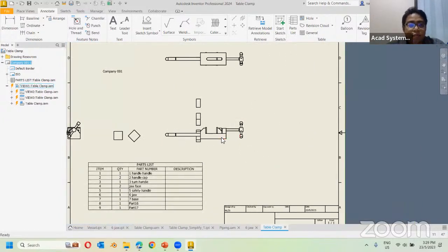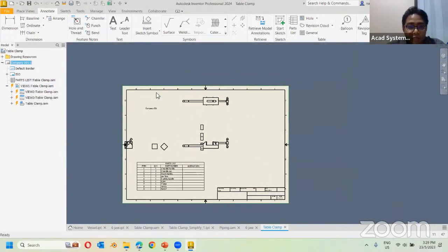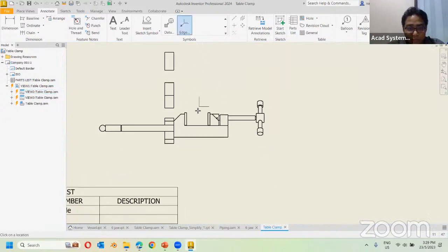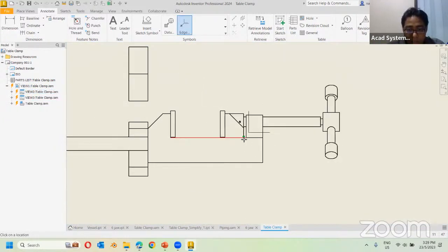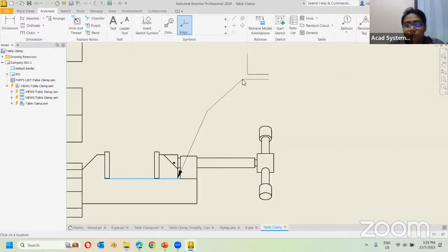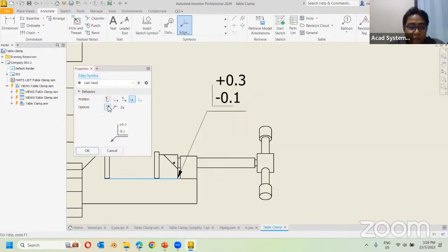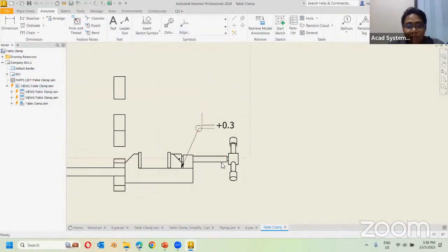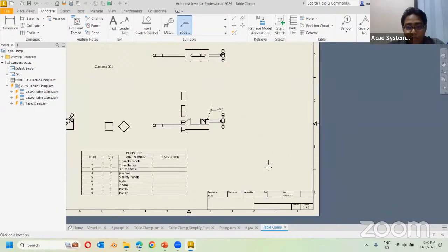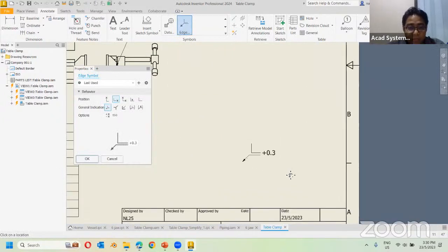And the last thing that has been updated under the drawing here is Autodesk has added the H symbol. So you can use H symbol under Inventor drawing. I can select H symbols, I select the area that I would like the symbol to appear, and I have a few pieces of information or properties that I can change for how I would like to see these objects. If I don't want to put it directly over here, I can also put it directly on top of my object over here.